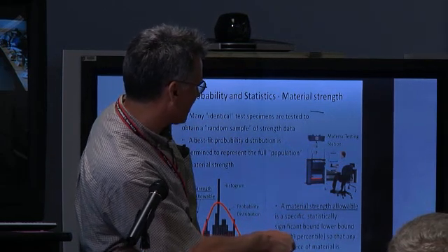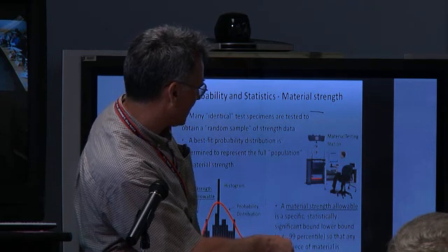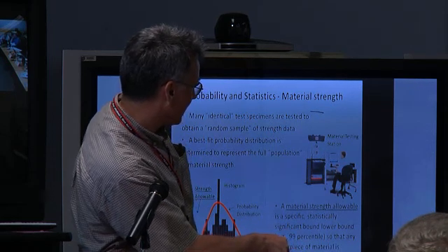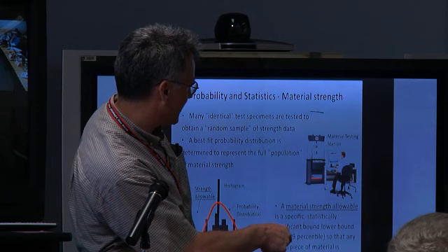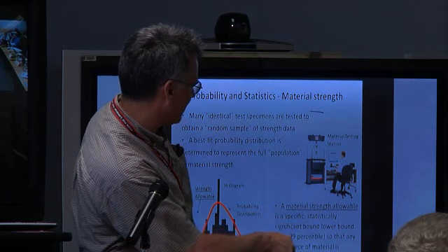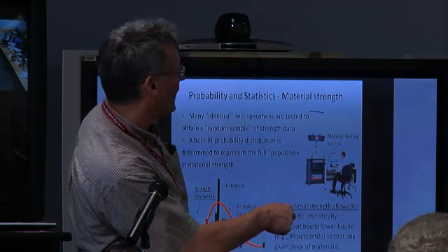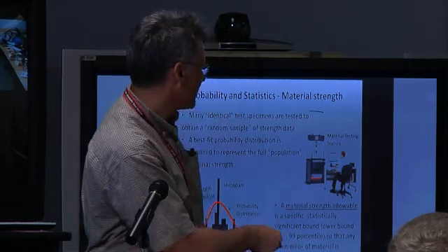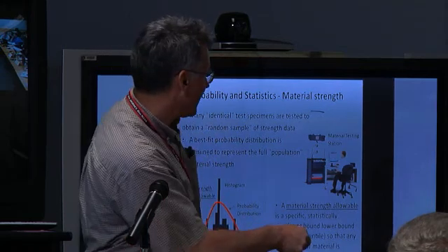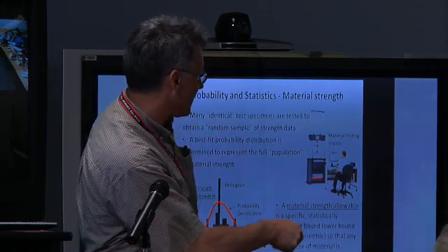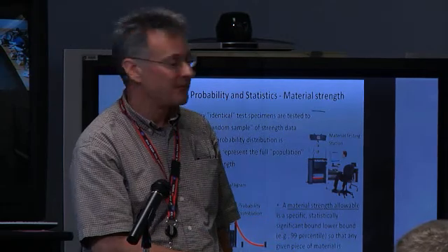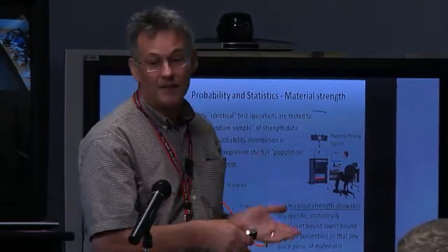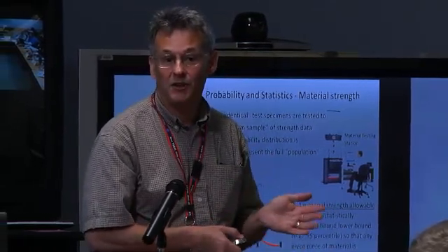In this case, 4 samples broke. A little bit lower level, we had a few more break. A little lower, in this case, fewer broke, and then right around here, about between 36 and 37, a whole lot broke. In this case, I'm going to guess about 60, 70 samples were tested, and this is the histogram. So basically, over each interval, this is the number that broke. Well, that becomes data now we can use to get a material property.